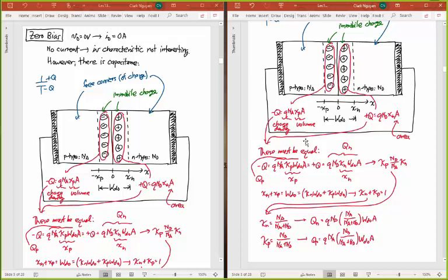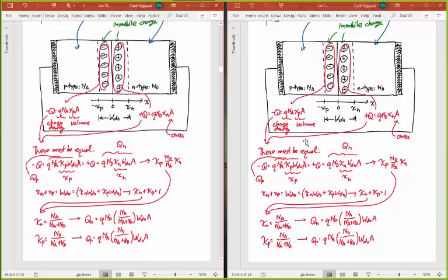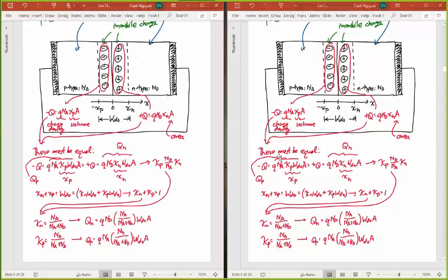Okay? So this is real physics here, right? We're looking at the physical situation that we have, the physical structure, and we're applying equations now to understand how much charge is developed across this depletion region for a certain width of that depletion region. So if I make this depletion region wider, this charge is going to go up. QP and QN will go up. And so that's the relationship I'm looking for. And now we know that that relationship depends quite heavily on the doping concentrations N sub A and N sub D on both sides, which we talked about at length last time.